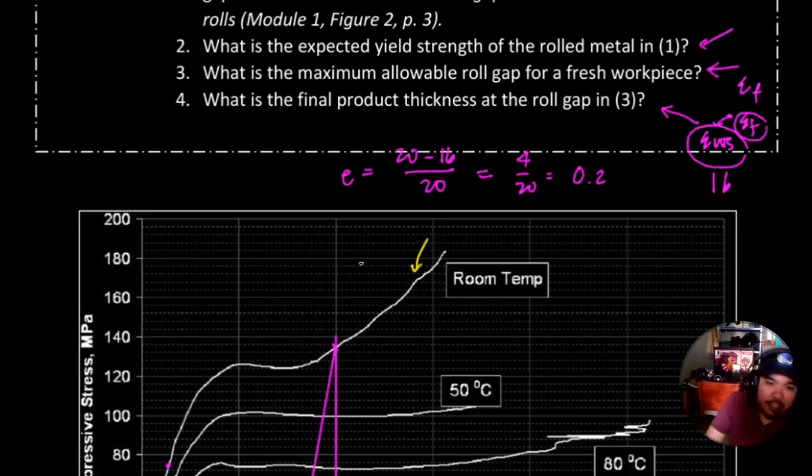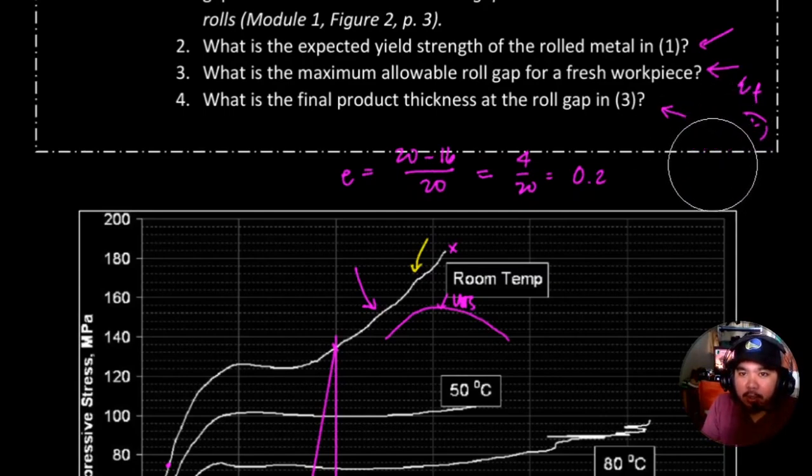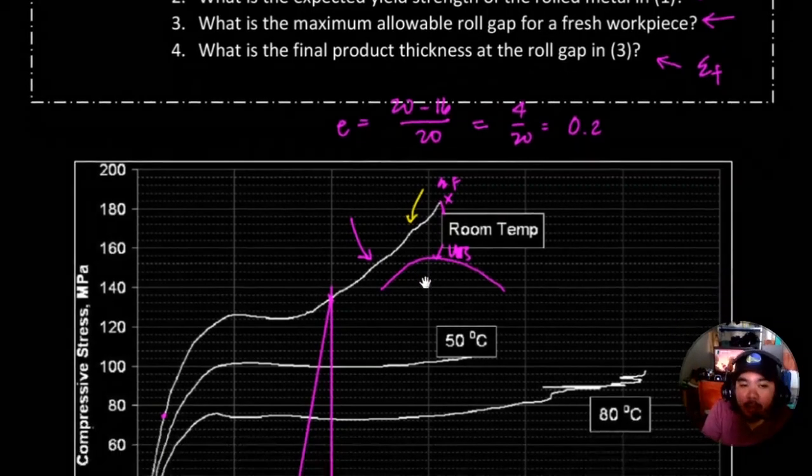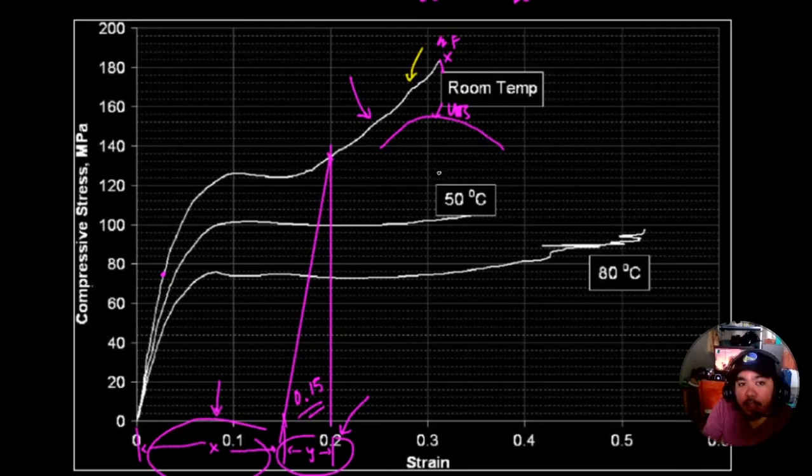Although here is a good manifestation of why in compression metals are always stronger in compression. You can see it in the graph that there is actually no plateau here. You don't experience a plateau. It just suddenly stops here, so I'm assuming this is its fracture point. So it has no UTS, specifically because it did not experience the necking behavior, or the necking behavior has no negative impact. Okay, I'll retract my statement. You can just use sigma F, this point. And you can use the parallel line technique over the whole curve to get the recoverable strain.